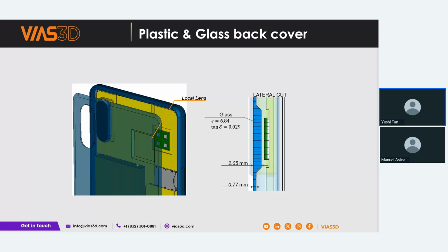So in this case, we're basically building a lens around the antenna array itself, right? So we can definitely propose something like that. And the idea is that we are making a lens concentrating the energy in certain areas, so amplifying it basically to improve the performance of the overall device.